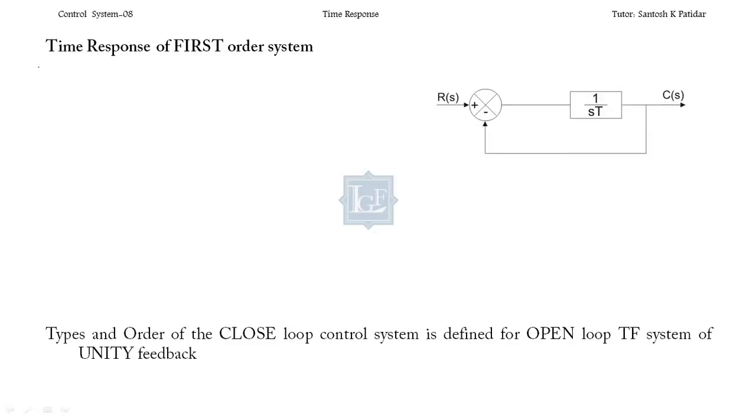Now instead of RC, if you have RL, so I'll take RL like this. This is the inductor over here, L. Here I'm taking the resistor R. Across R, I'll take the output like this. Vi, if I convert into the Laplace domain, this will become Ls. Here it is V0 S.